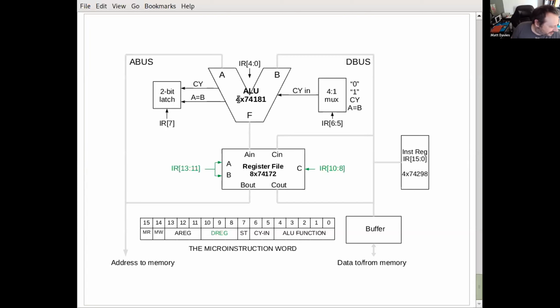Yeah, I mean, there is some advantage of low gate count CPUs, even on FPGAs. You can use them as specialist processors. Obviously a lot of the big FPGAs let you fit on a massive number of gates, but it's sometimes an advantage to have a very small general purpose processor implemented in a few gates on an FPGA.